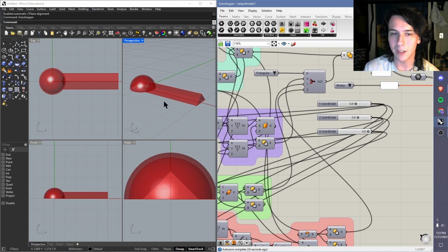If you're trying to interact with what you've created in Grasshopper using Rhino, don't do that. We'll get to that in a bit. You can see the way that my changing of this slider changes the dimensions of the part, and these live update so I can see different iterations of this part and decide on what I like.